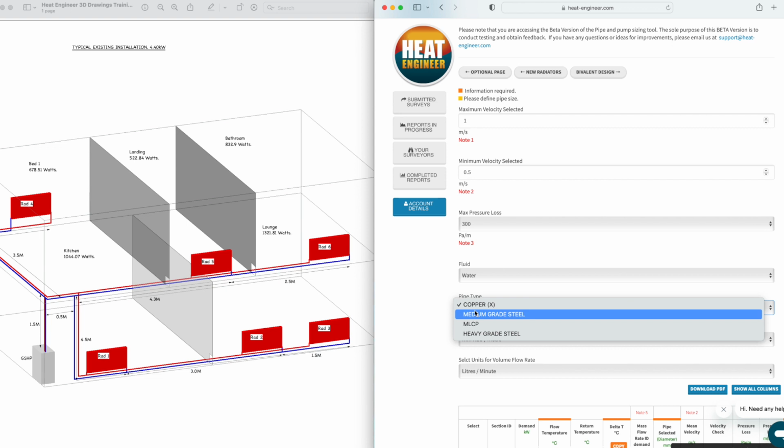And I want to try and prove in this tutorial that a lot of low temperature designs, whether it's a heat pump or a boiler or whatever it is you're changing to, you're trying to run at high flow, low temperature. So instead of using a DT20, a difference in temperature of 20 degrees across a flow and return, we're going now more to a DT5. So we're quadrupling the flow rate running through.